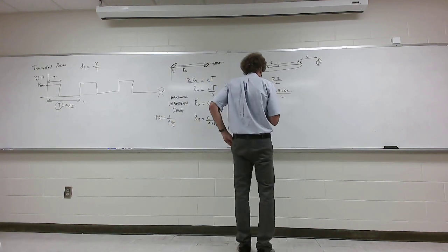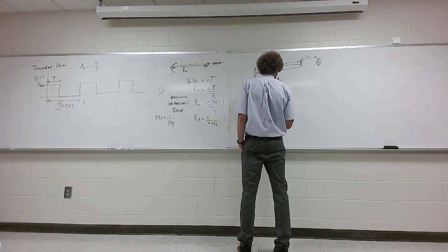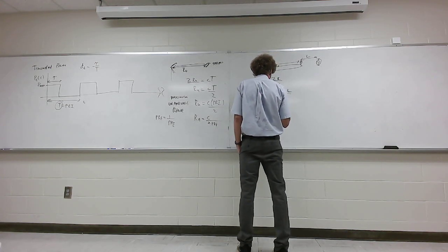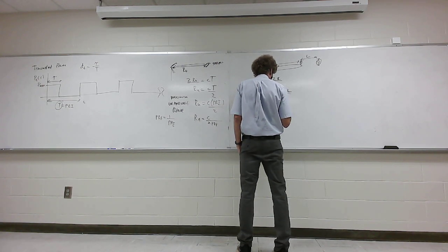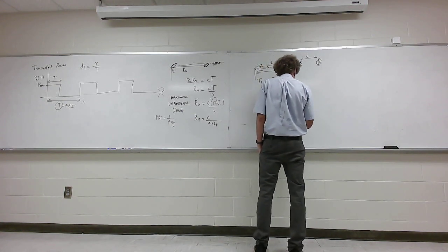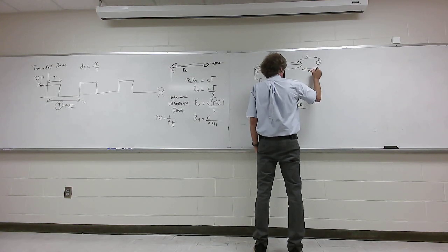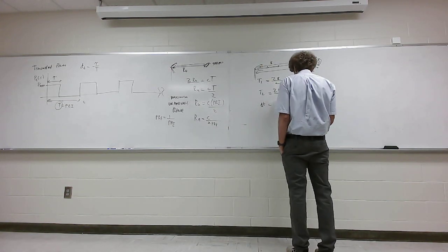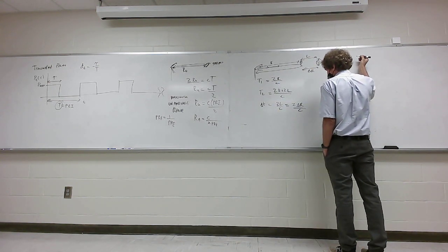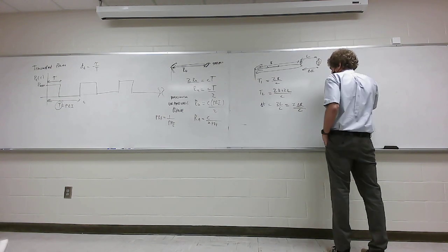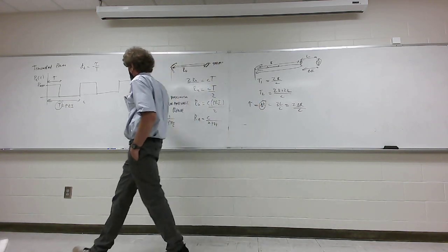If I subtract those two, I can see that the delta T would be equal to 2L over C. And what this actually turns out to be is 2 delta R, because L really is a change in range, telling me what I can resolve. And that means this delta T is associated with this value tau right here.